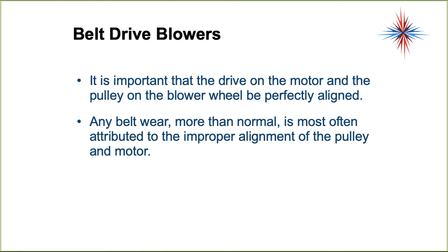It's important that the drive on the motor and the pulley on the blower wheel, when you're dealing with belt drive blowers, be perfectly aligned. Any belt wear more than normal is most often attributed to improper alignment of the pulley and motor.